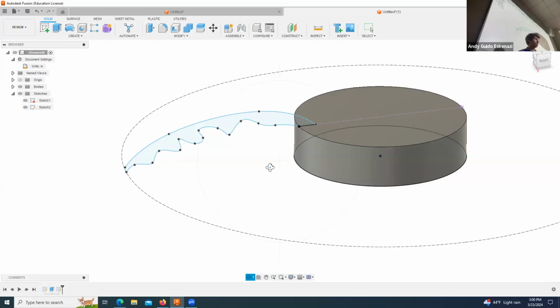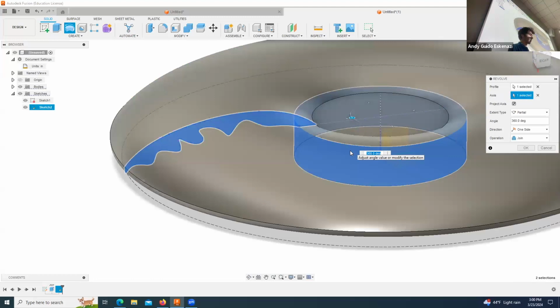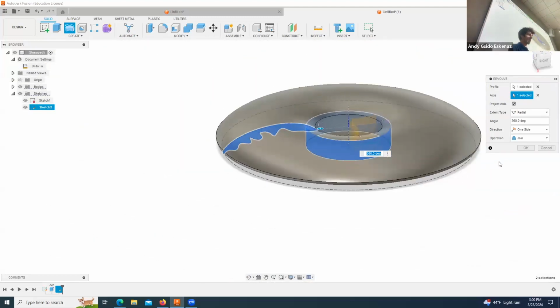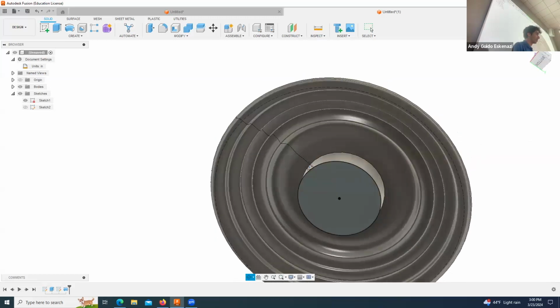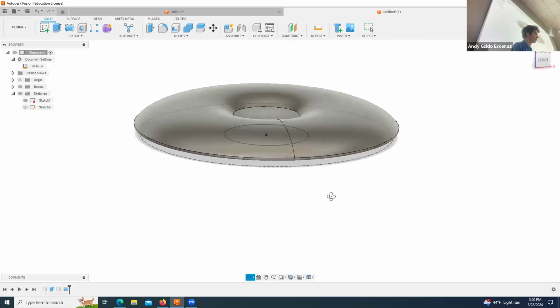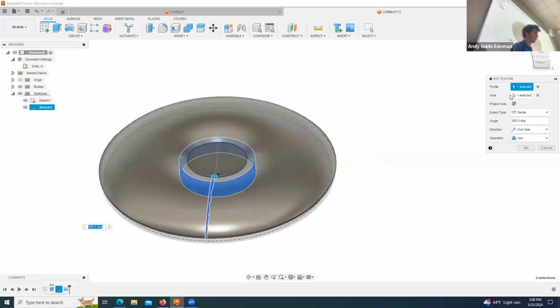All right, so we're at this point. Now go to where it says revolve. In create, it's that command revolve, or otherwise click on create and it should be revolve. You can select this profile in there and then this axis. It's going to do this massive thing, and I'll say, okay, let's do that. Just click on the cylinder body. So it makes a massive champignon like this. We can go here, edit feature, and again I selected the profile and that axis.